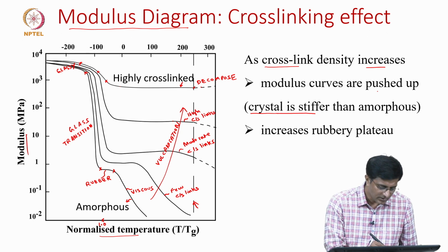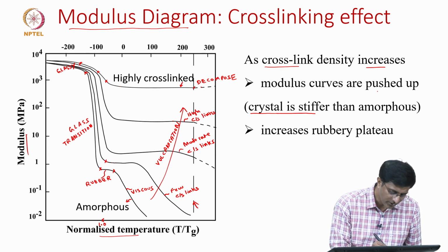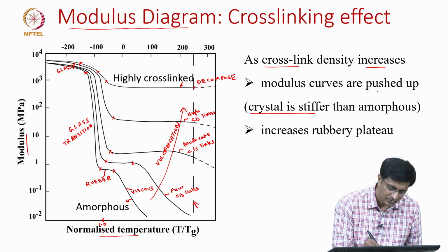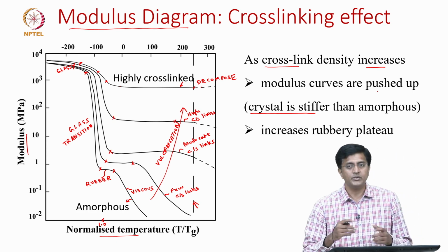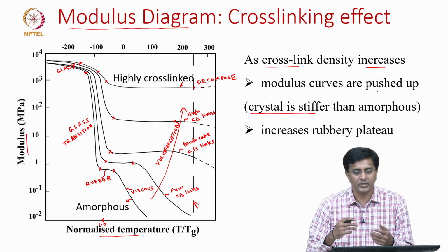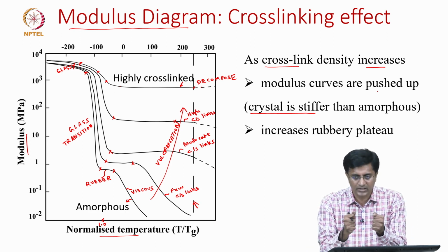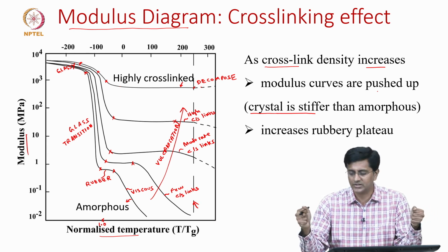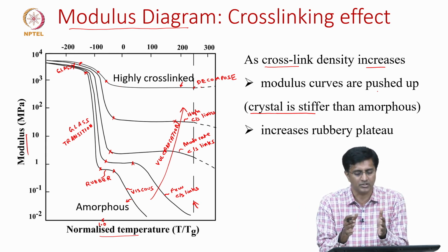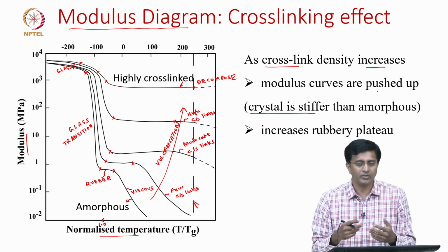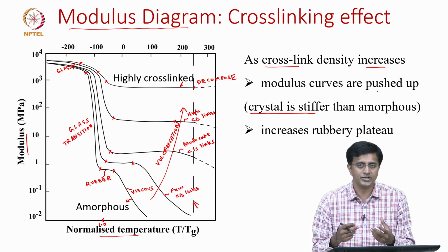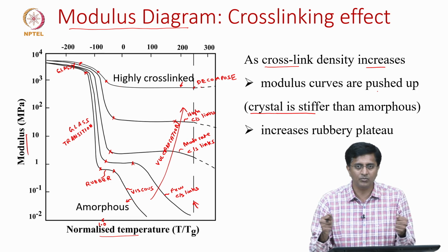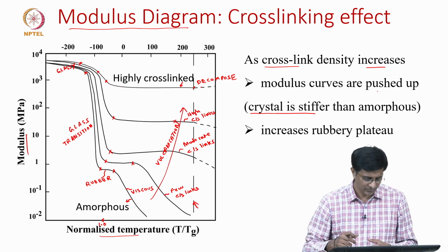And we also see that the amount of rubbery behavior increases. So, what is rubbery behavior? It is where the polymer stretches for large strains and when unloaded it comes back to the original shape. So, if we add more sulfur, that is when we can see more of this rubbery state.